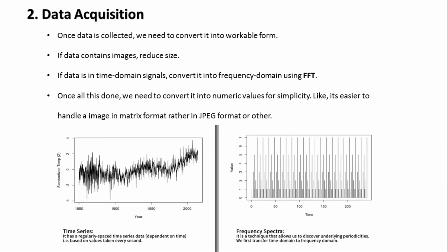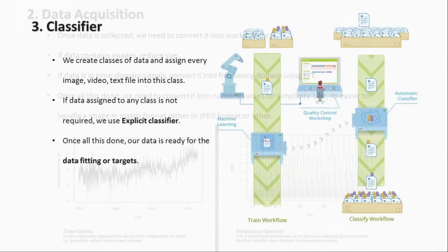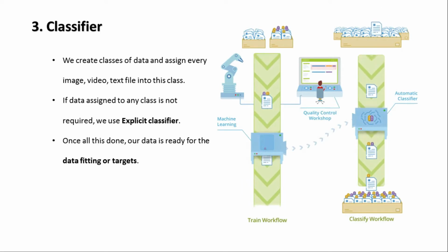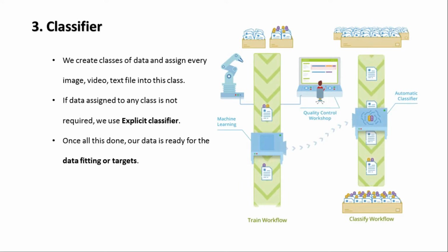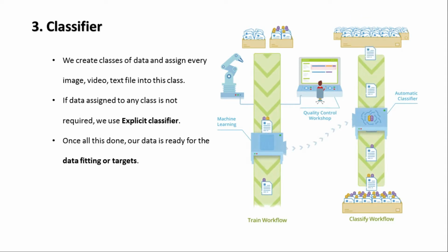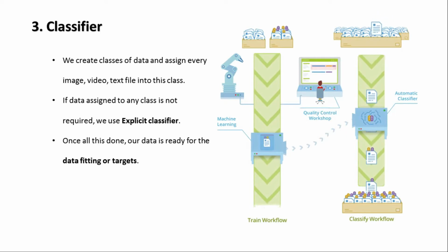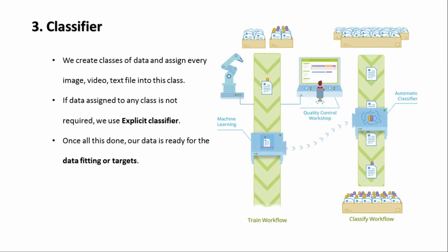After learning about data acquisition, we will now look into a classifier. Now, what is a classifier? The data converted from time domain to frequency domain will help us in extracting some useful features, also known as condition indicators. These condition indicators differentiate between healthy and faulty conditions. But these features do not tell us what part of the machine needs repairing and how much time there is until failure. Now, a classifier can detect anomalies and detect different types of faults so you can gain insight into what part of the machine requires attention.